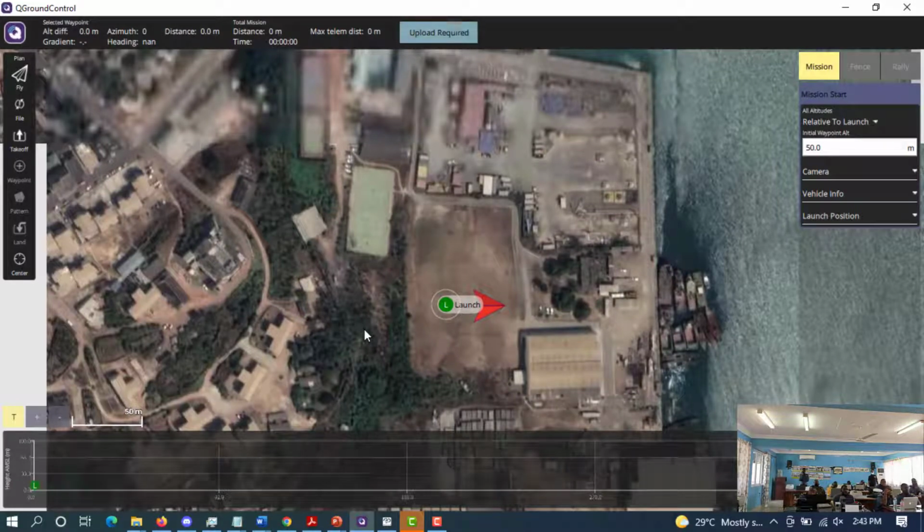But bear in mind that we have plus or minus 10 degrees to play with. That plus or minus 10 degrees has some limitation in terms of altitude buildup. If I want to go to 500 meters, it is very bad for me to move straight from 60 straight to 500. Rather, I can build it up by keeping my pitch within plus or minus 10 degrees.